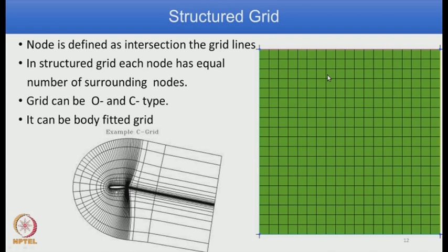So, this is an aerofoil and you generate one family of lines close to the surface, following the surface of the geometry. So, you get lines with a shape similar to the geometry shape, and another family of lines running perpendicular or in another direction, emerging from the surface. You are seeing here all these lines almost vertical after some distance, and here almost horizontal, which is another family of lines.